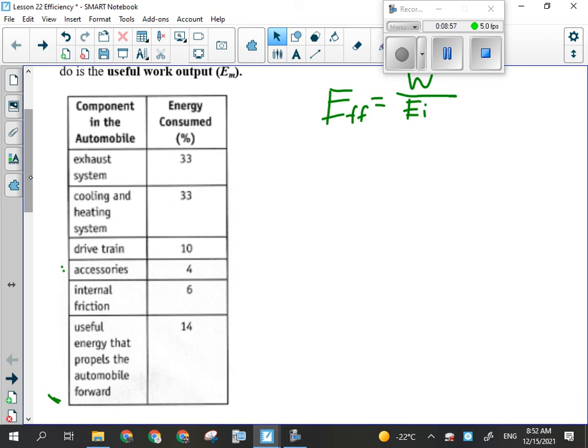All right? Now, your car generates so much heat because, I mean, what are we doing? Burning gas. It gets hot. That it has to use 33% of the energy in its fuel to power the heating and cooling system that keeps the engine from destroying itself. There's a little belt that comes off of the main drive shaft of your engine that runs the alternator and the water pump. The water pump pumps coolant, that green stuff, all through the engine block, absorbing heat by the second law of thermodynamics, pumps it into the radiator, which then blows the hot air out into the surroundings, helping to cool the engine. That uses 1/3 of the energy your car generates. That whole system.